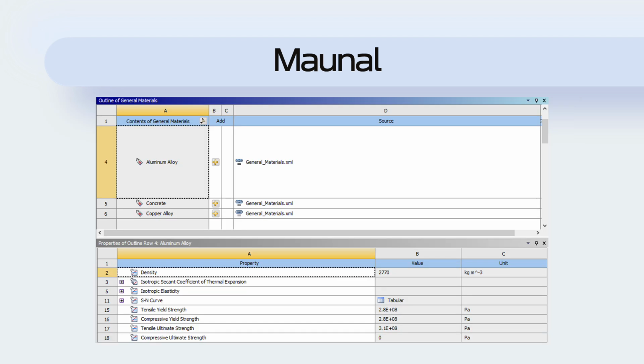By reviewing the material properties, you can see the detailed information. These details can be adjusted by setting the desired density, yield strength, and stiffness, allowing you to tailor the material properties to fit your design or the specific requirements of the object you are working with.